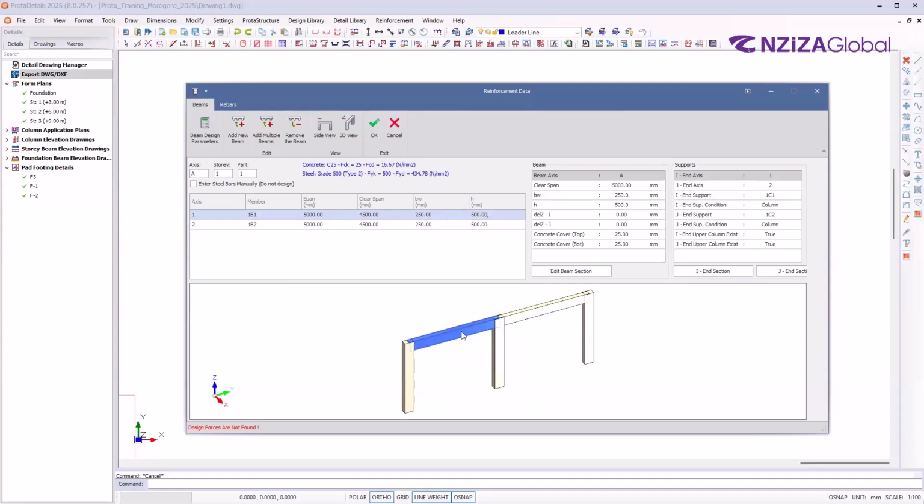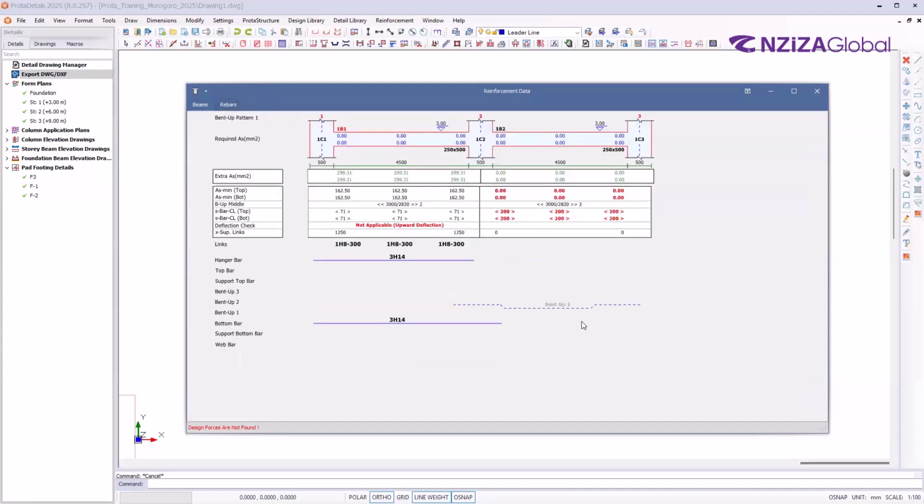You have to fill the B and the H. Okay. After doing so, you will come back here to the rebars. Okay. Then you have to put the reinforcement here. Okay. Let's say we have 3 reinforcements at the top and 3 here. Okay.